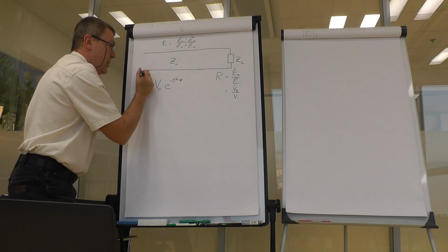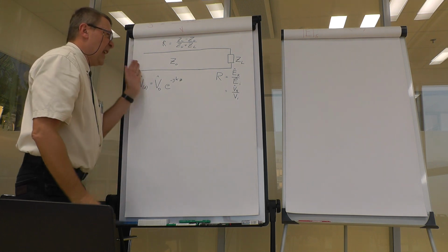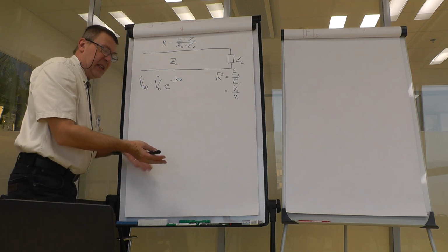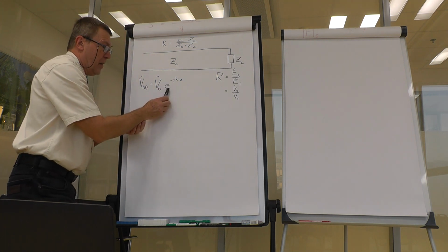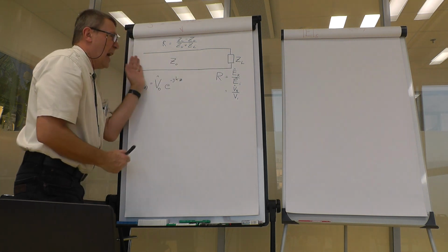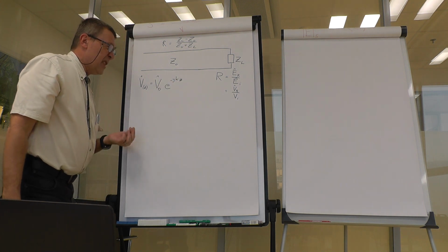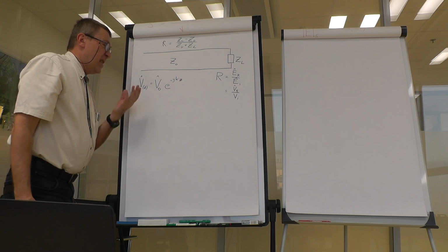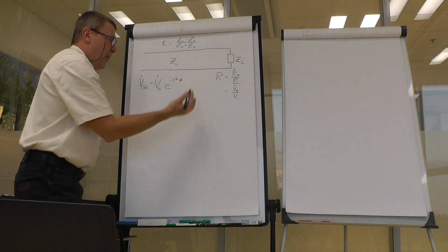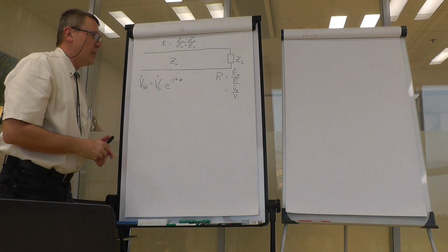Well, those both are phasors, of course. So we have a wave traveling along the line, and we can decompose that into just phase change along the line and the decrease of magnitude, and that is then the equation for the phasor of the wave traveling along a transmission line.